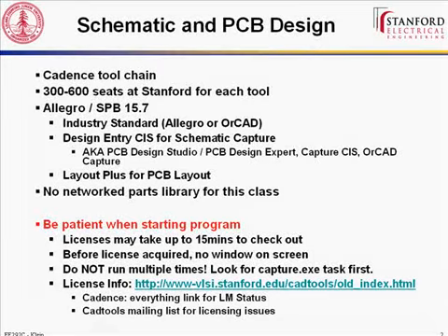There's a website that's on the slides that you can go to. It will give you information about all of the CAD tools we have. This includes VLSI design, for making ASICs, things from Mentor Graphics, things from everybody. Look for Cadence. Remember that the Allegro tool set that we're using is by Cadence. And you can check the license manager status towards the bottom. It has a little link that says Cadence, and it'll say status users or everything. So you can click on that and make sure the license servers are actually up and running.